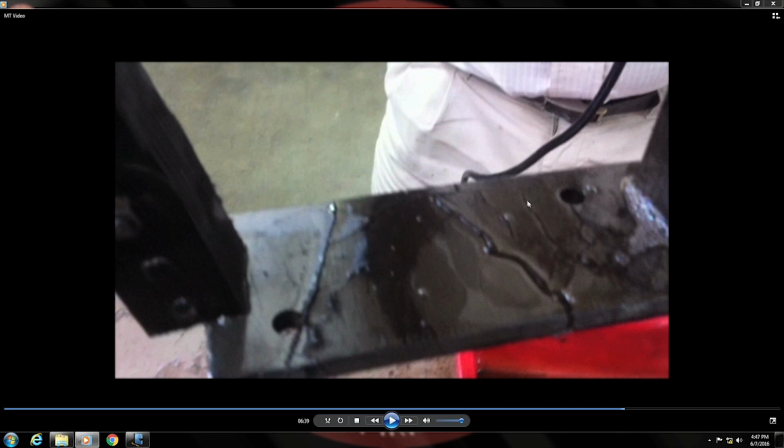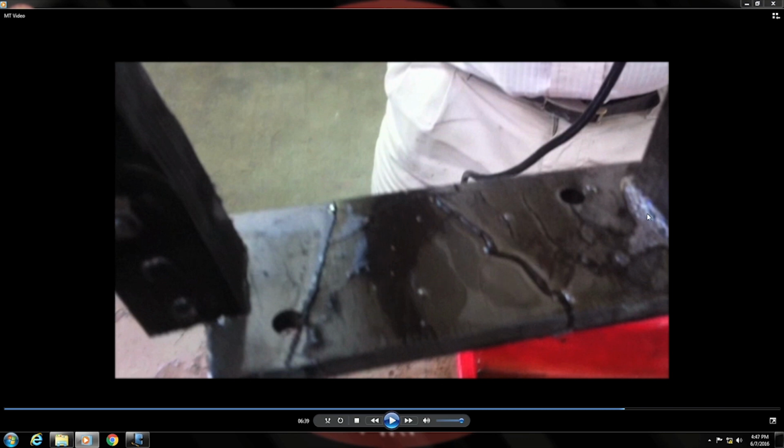And again I would like to show you the orientation of this particular crack. So, this is one leg of the yoke and the other leg is over here. And if you remember, I told you, if you connect these two legs by an imaginary line like this, okay, so that will be the direction of the field, and now you see this crack is perpendicular to that direction, okay, and it is giving a very strong indication.